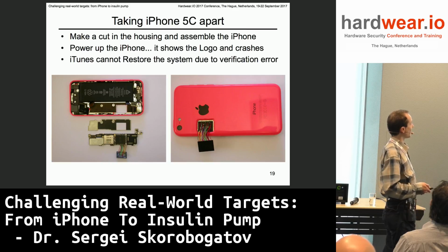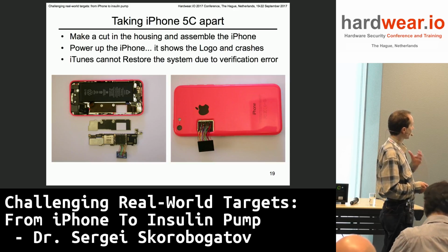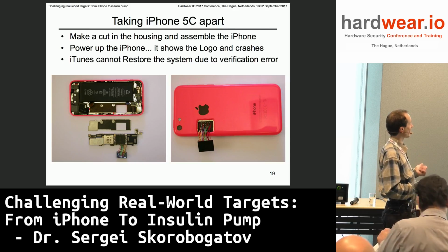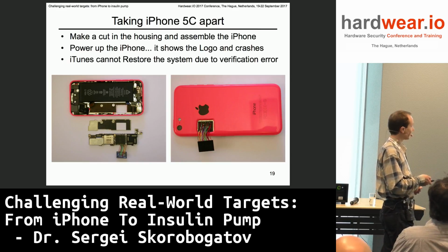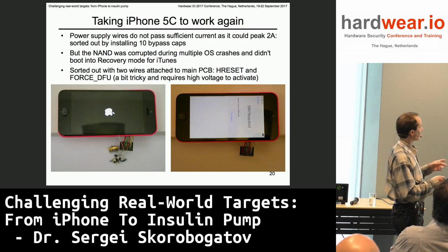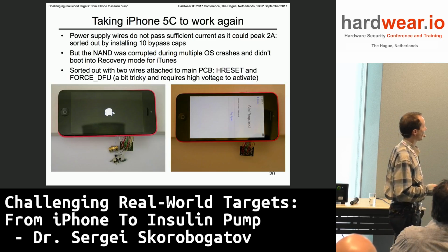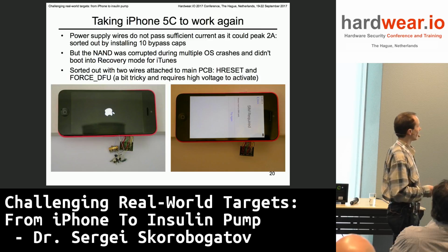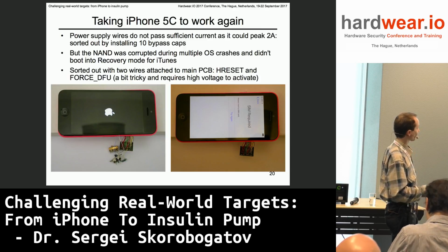But here came the first problem. When I started the iPhone, I saw the logo and then it crashed. And then I also tried to use iTunes to restore it, and it came with a verification error. So the problem was that those thin wires were not able to carry quite a high current, because at peak time it requires up to 2 amps.